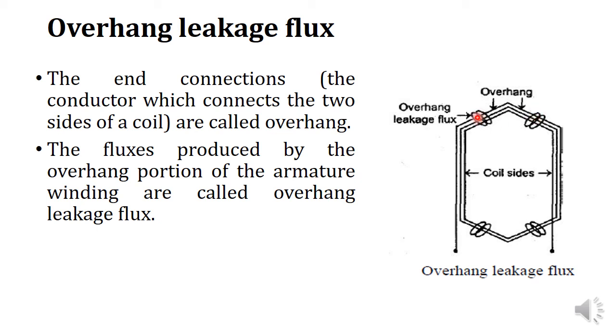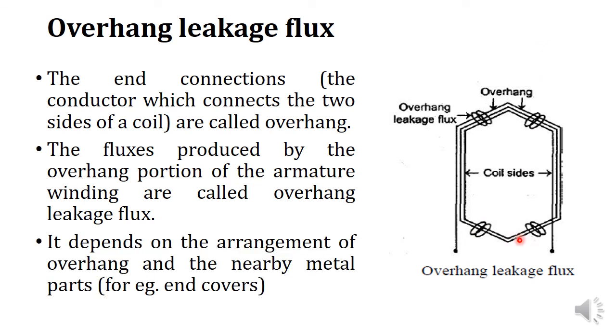So at this end, these are the overhangs, and at the other end, these are the overhangs. So on both sides, there will be overhang leakage flux. And overhang leakage flux depends on the arrangement of the overhang and the nearby metal parts, for example, end covers.